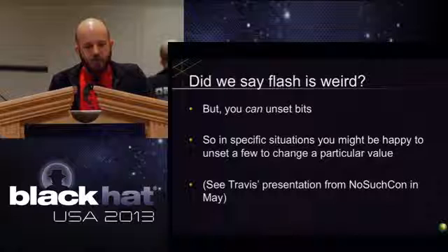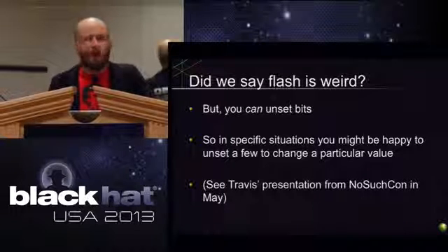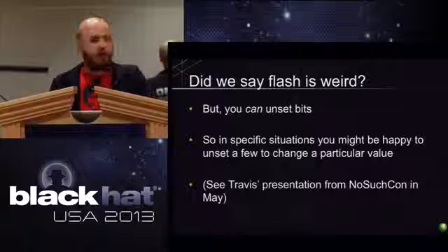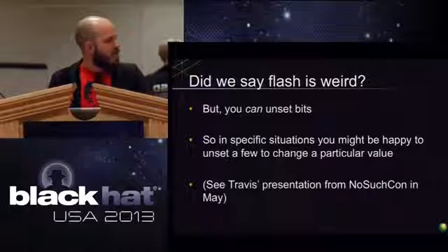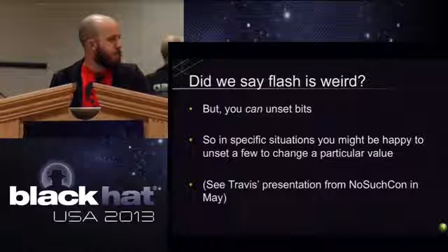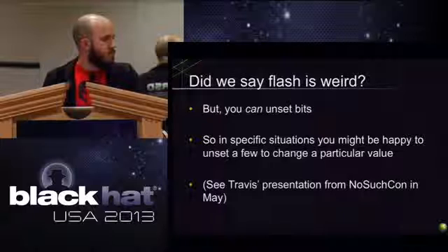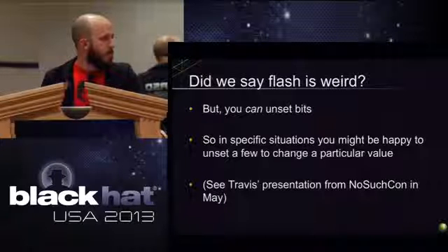Right, so we can unset bits. In certain specific situations, you can be happy with not having to do that mass erase trick. You can craft your data so that, in a binary 1 and 0 format, you can still flip from a 1 to a 0 and then recraft your data. But that is a huge headache.